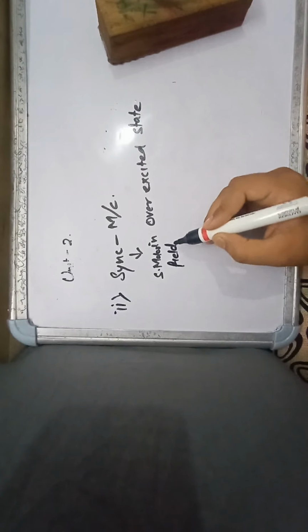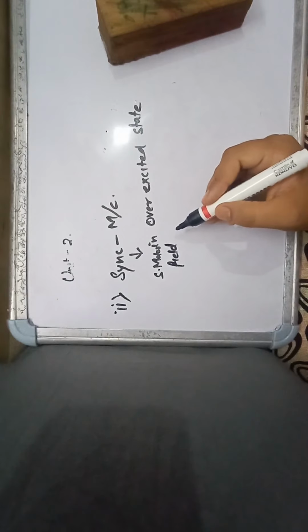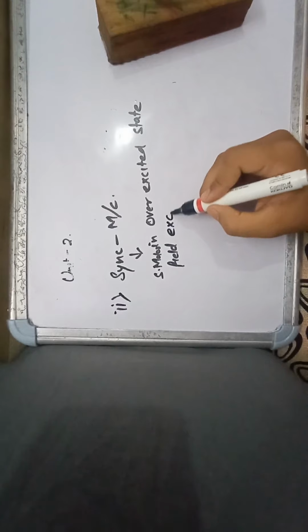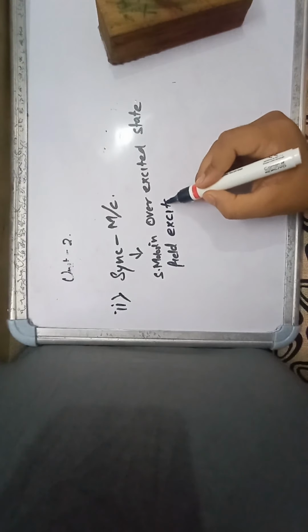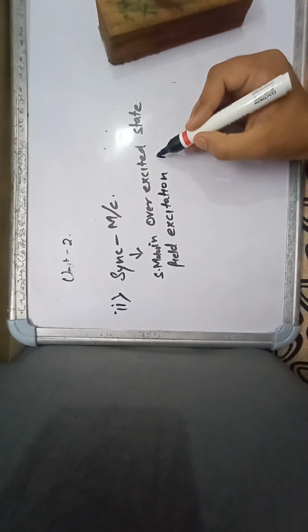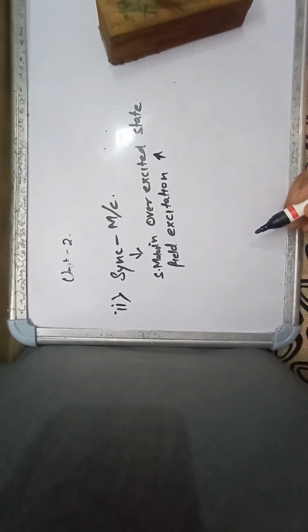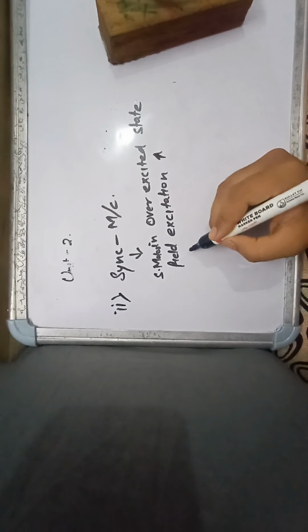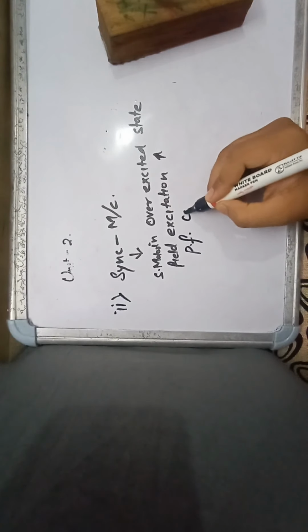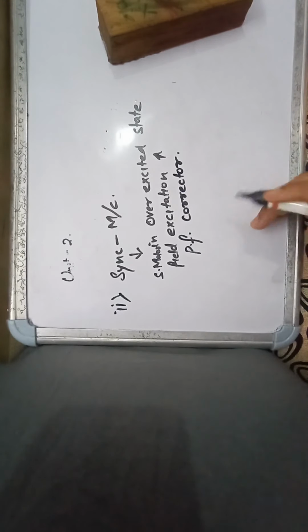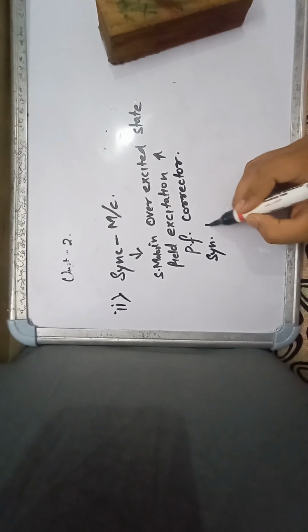Better read the machine topics and their inverted V curve, the most important part of electrical engineering. So this is your field excitation. If you have more field excitation, if you operate the synchronous motor at overexcited state, then it acts as a power factor corrector device, or you can also say a synchronous phase advancer.